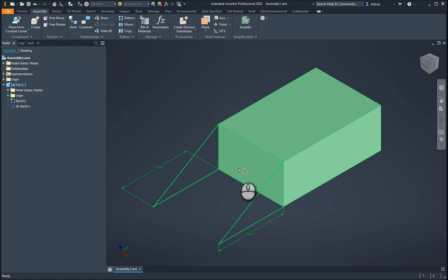In today's video, I'm going to show you how to create a frame using Inventor's frame generator. When I refer to frame, it would be things like I-beams, channels, etc. When we're creating a frame generator, it needs to be in the assembly environment.